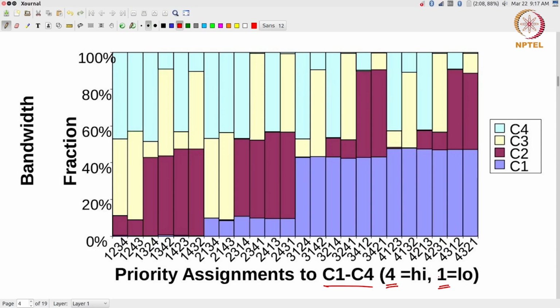One way of thinking about this would be C1 to C4 need to transfer a very large number of bytes from their individual processor, or rather are generating data that needs to get written into 4 slaves. So they are not generating data at regular intervals, they already have the data available to them. So anytime that the bus is free, they can write the next data, okay?